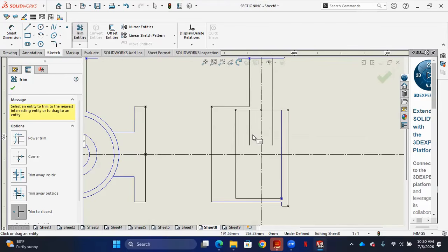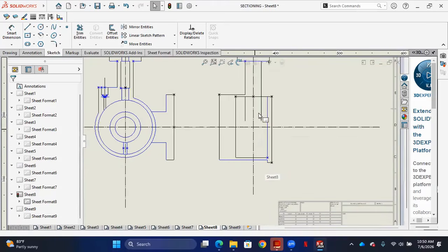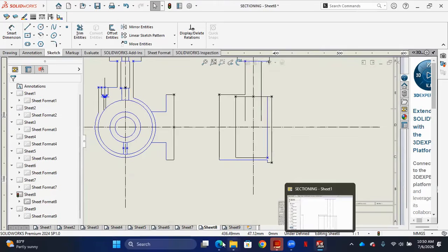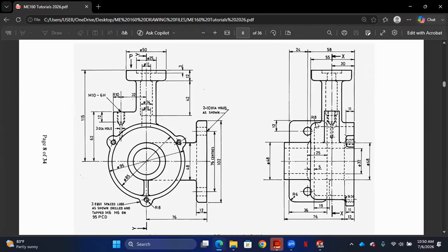Now it's left with the inside. So basically, I don't even need this line. So let me check if I need them. I've extended this line and then this line. I don't actually need these extended lines from here again. So I can clean them and then draw the inside, because the inside I'll need. And if you check the distance, this hidden line over here is the same thing as what is here for this circle.